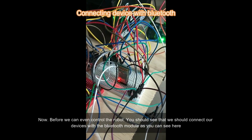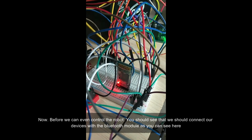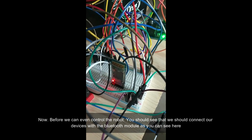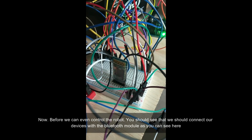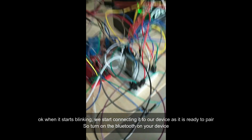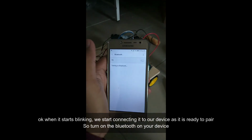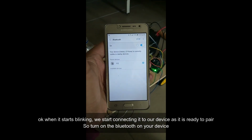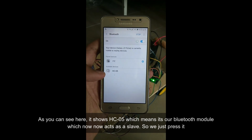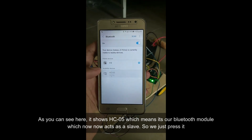Now, before we control the robot, we should connect our phones, our devices, with our Bluetooth module. And you can see here, when it starts blinking, we should start connecting to our device. We just have to turn on our Bluetooth. I can see here it shows HC05. That means it's our Bluetooth module, which now acts as a slave. So we just press it.